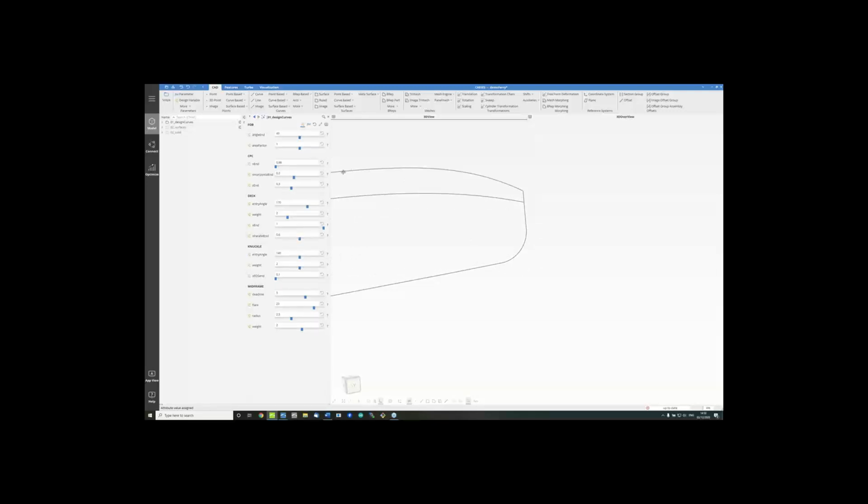We go to the CPC curve here and take a look at the stem. We can modify the radius at the tip here. We can also modify the elevation of the center plane curve in this region, or modify where the flat of bottom might end or start. We can look from the top at the vessel and take a look at the outline of this deck contour here.